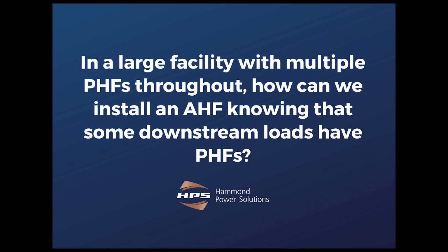When it gets down to a large number of small VFDs, it may be impractical to put a passive harmonic filter on each VFD. But if you have some significantly sized VFDs, you could put passive harmonic filters on those individual VFDs, and then any other harmonics from VFDs or other sources could be cleaned up by an active harmonic filter.